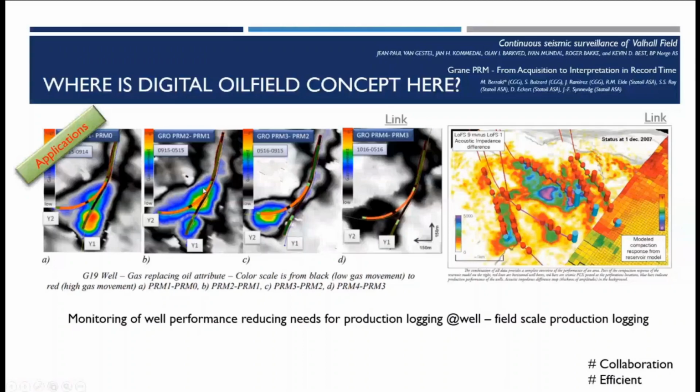You see that now, you see that we have got changes out over here during this time period. Slowly it moves up out over here. There is no more space out over here for the gas to move. So it moves in the toe much more, but nothing happens here. Another 6 months passes, we see still very little happening here, and nothing happens much more because it's a gas breakout all across the well, where you have got production screens. So that's telling us something, that there is something funny out over here. I'll explain a bit in the next slide.